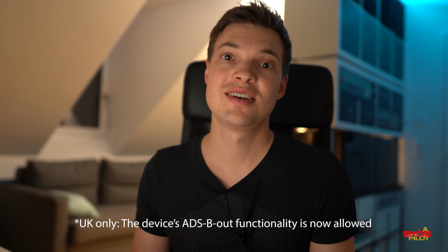On the other hand, for example, there's a popular small little portable device out there which will be able to send all FLARM and ADS-B targets into your navigation app like SkyDemon or ForeFlight. It costs only 500 euros plus some license fee for the FLARM licensing. That sounds awesome. Now, what you might not realize in the first moment is that this device alone won't broadcast your position in any way to others. So if we all had this unit, we would all receive, but nobody would send. So in the end, we all see nothing, even if we have Mode S transponders on board.